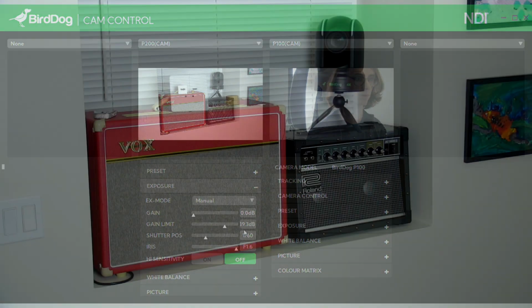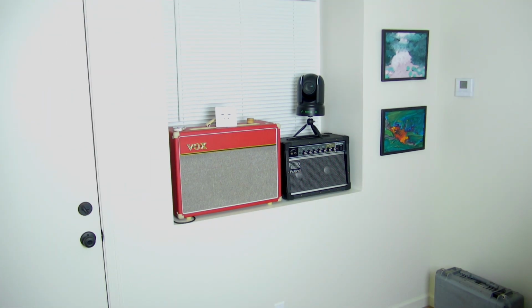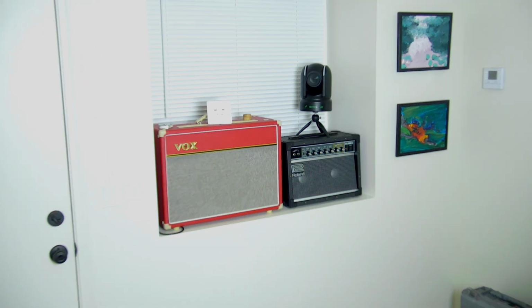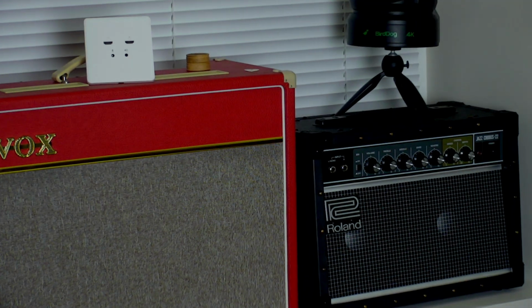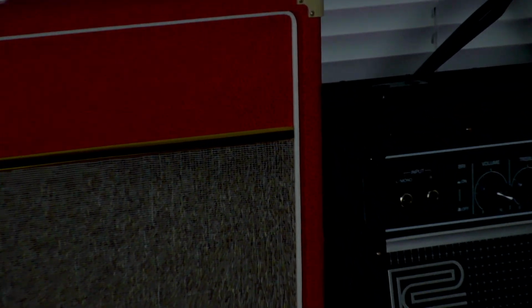If we switch over to the image of this P200, we can go fully wide and we can see that the blinds and the wall plate are now overly exposed. However, when I go to zoom in, we notice that the image gets a little bit darker, and that's because the iris is stopping down as we zoom in through that lens, and we get more and more zoomed in until you notice that it doesn't actually get darker anymore. So at that point, we actually hit the final stop, as wide open as it can be at that zoom range.